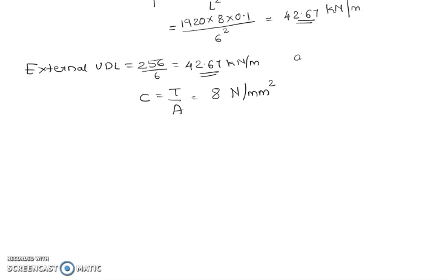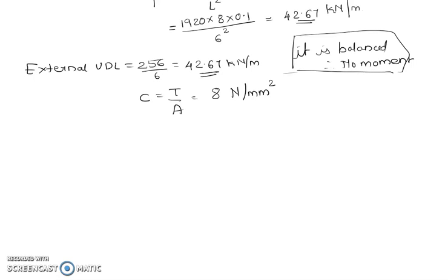So as it is balanced, therefore no movement. Okay, and because there is no movement, what will the beam experience? It will experience pure compression, uniform compressive stress, equal to T by A, which is 8 Newton per mm square. Let us see part B here, that is external UDL